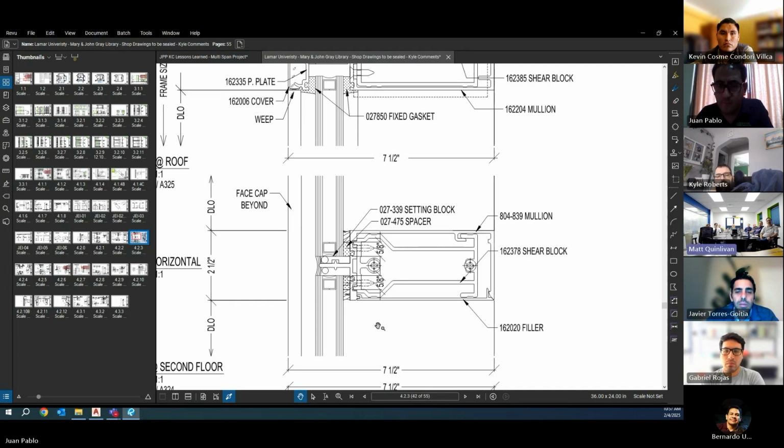Yeah. So if you splice below this horizontal, your glass is still adhered to the frame above and below the splice. Actually, it's resting on the horizontal below, and then it's siliconed up to the next horizontal above. So if there's any movement, there's no way to really accommodate that with this type of horizontal.